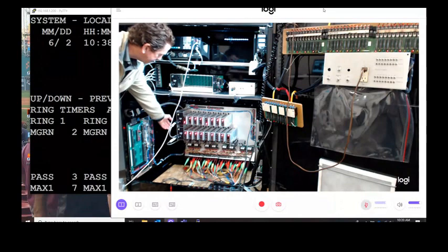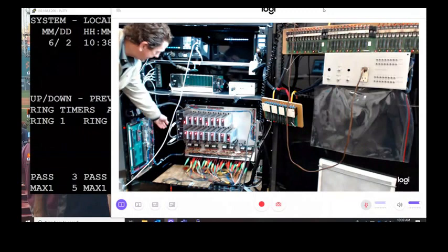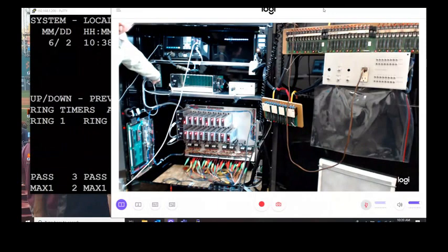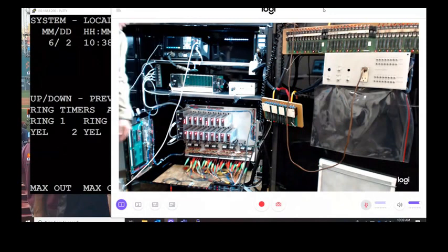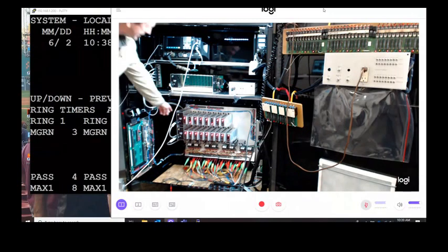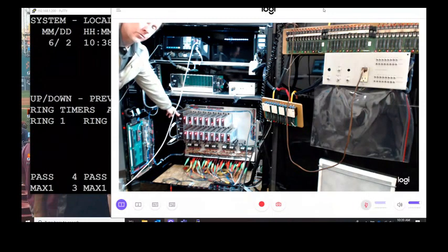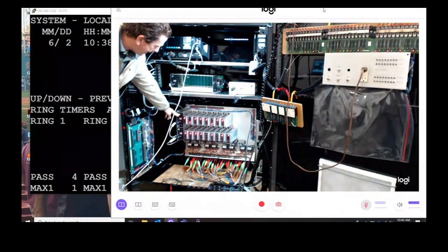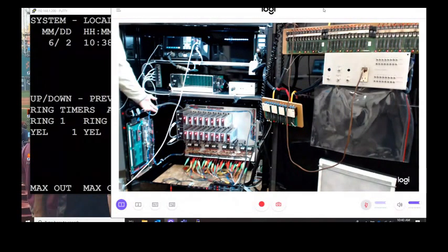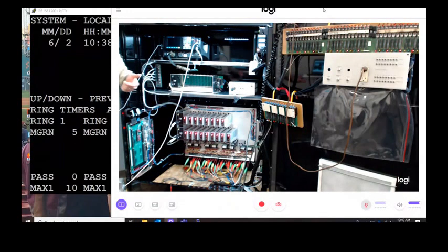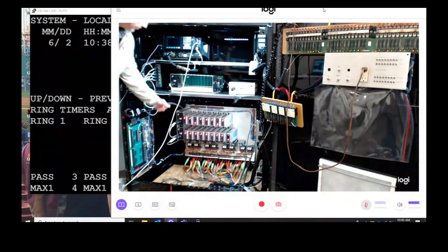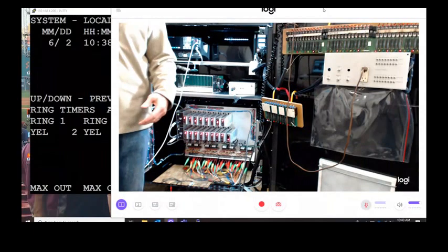The other thing is it's also confirming that my cable is good, that I have a good connection from here back to my hub assembly. So we're killing a couple birds with the same stone. If one of these is bad, especially if it has a ground issue or a 24-volt DC issue in it, it shuts down this whole bus. So it makes it seem like I have 3 bad BIUs or 2 bad BIUs, but really I just have 1, or 1 cable. I'm trying to isolate if it's the component or if it's the cable.